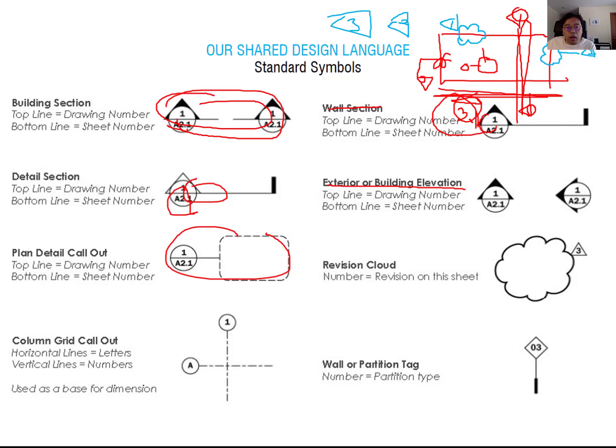And then on the title block, usually there is a revision area. So you can say this is revision 1, this is revision 2, this is revision 3, and then you add the date of each revision: when the first revision was, when the second revision was, when the third revision was. You have to write it down, so it is much easier to track information. Okay. Of course, your drawing has to include the grid line. This grid line mostly comes from your structure line, so we mostly communicate your drawing location following this grid line.